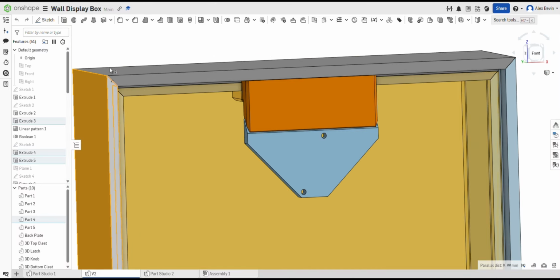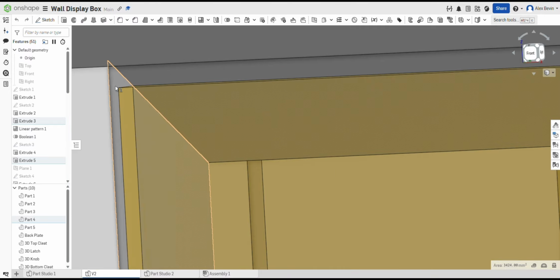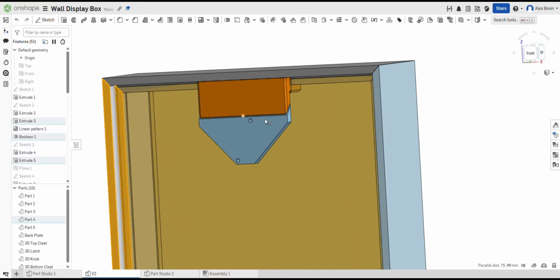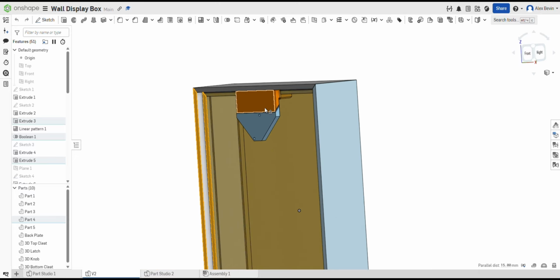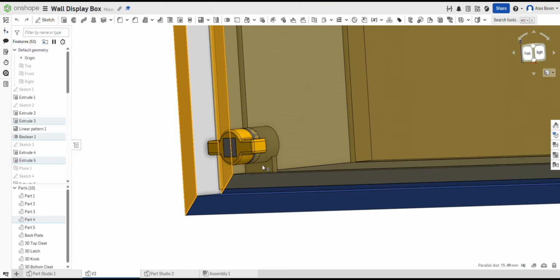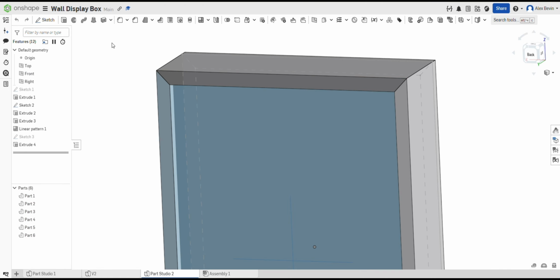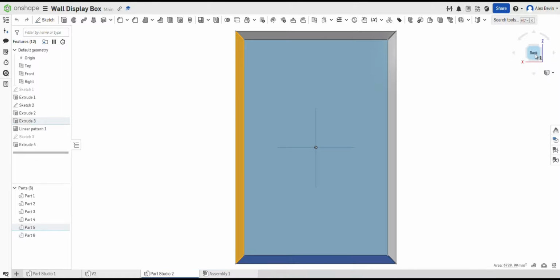Now, the plywood is 16 millimeters thick, so the rebate comes in 8 millimeters, basically halfway through the plywood. That gives a strong border around the perimeter, and it also creates space for the cleat and the 3D printed locking mechanism. The key numbers for this back pocket are 8 millimeter border thickness around the perimeter, and a 15 millimeter pocket depth from the back face. That's deep enough for the cleat and lock, while keeping strength around the edges.